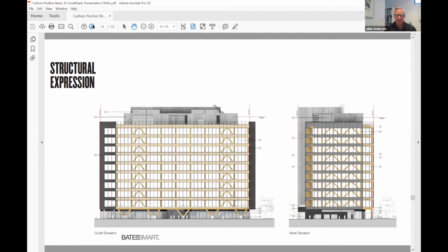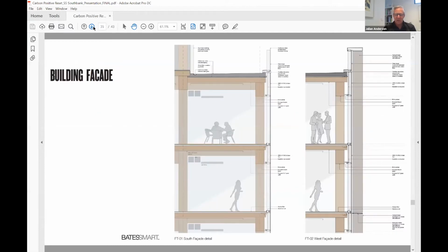Due to the side core, the stability of the structure was transferred through the diaphragm CLT floor and the braced frames around the perimeter of the structure, which you can see in this elevation. This is a detailed section. Our typical floors are 3.7 metre floor to floor with exposed surfaces, and also importantly exposed cross-laminated timber floor soffits.